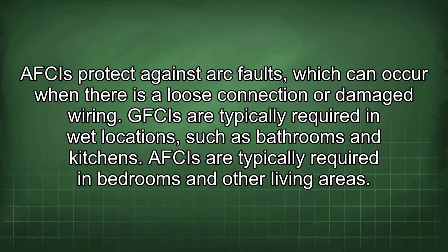GFCIs are typically required in wet locations such as bathrooms and kitchens. AFCIs are typically required in bedrooms and other living areas.